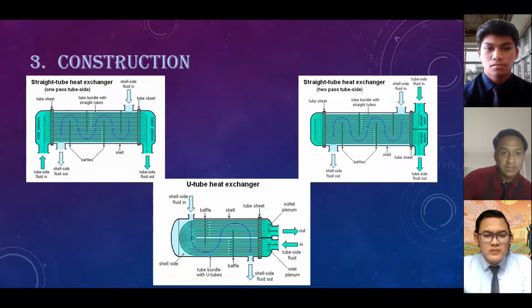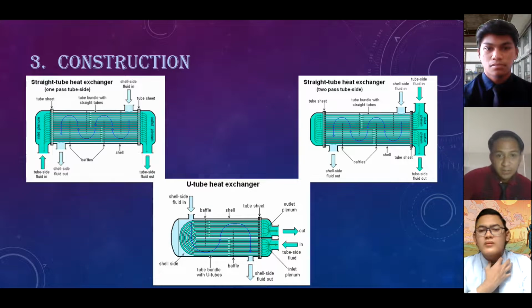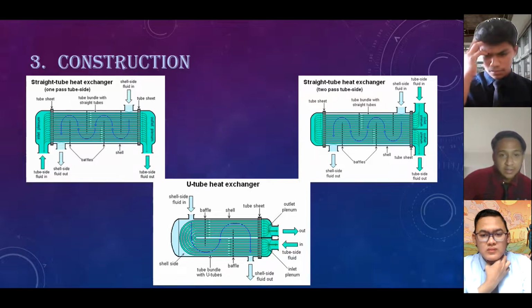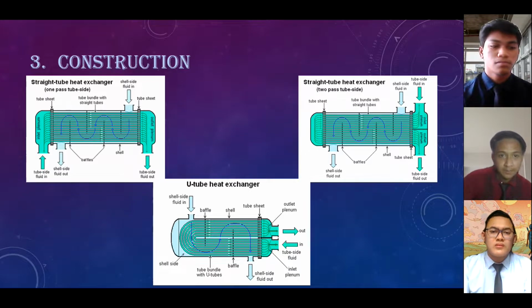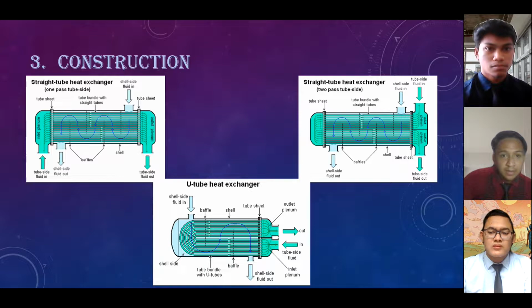Straight tube exchangers: surface condensers in power plants are often one-pass straight tube heat exchangers. See surface condenser for diagram. Two and four-pass designs are common because the fluid can enter and exit on the same side. This makes construction much simpler. They are often better at directing flow through the shell.